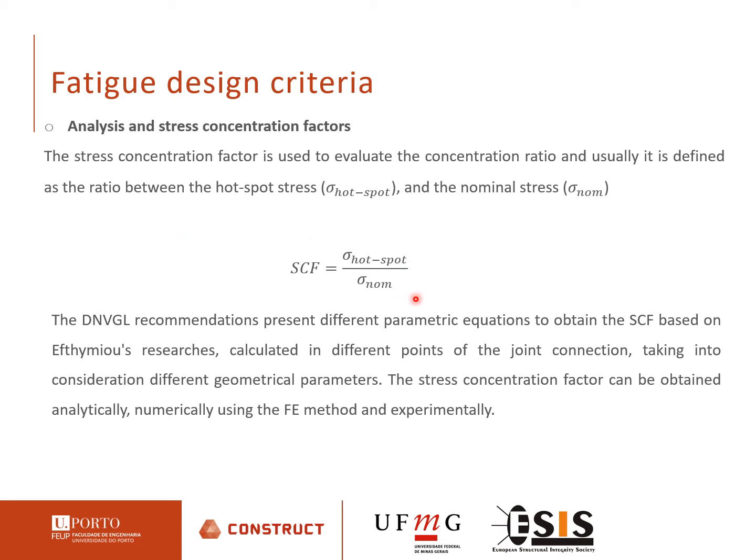The DNVGL recommendations present different parametric equations to obtain the stress concentration factor based on Efthymiou's research, calculated at different points of the joint connection, taking into consideration different geometrical parameters. The stress concentration factor can be obtained analytically, numerically using the finite element method, and experimentally.